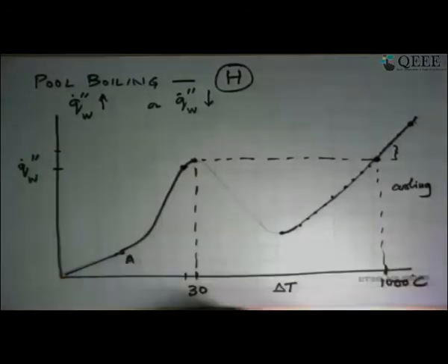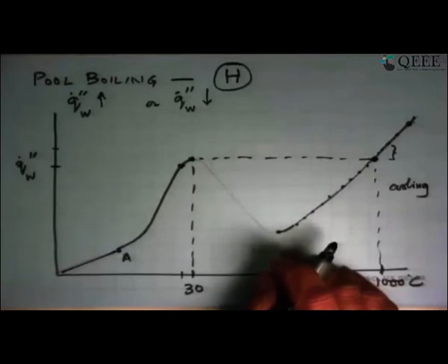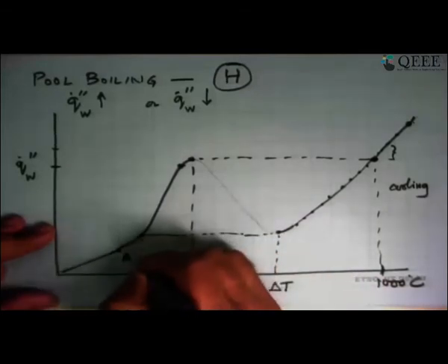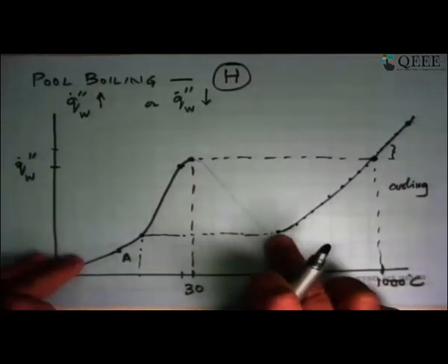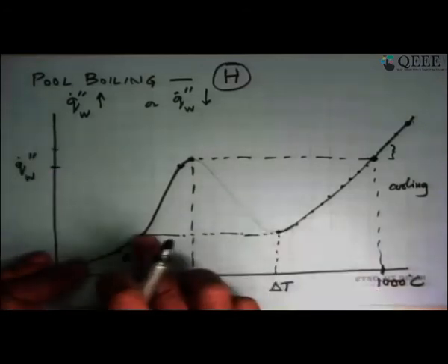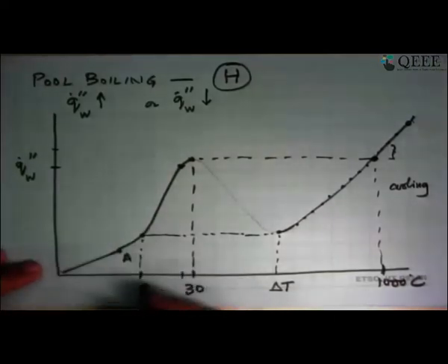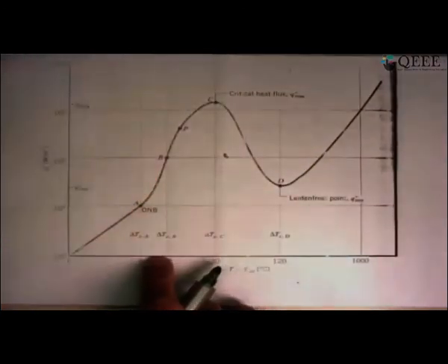So we reach that point because you are coming down this axis, and then if you slightly reduce the heat flux at this point, it will jump from here. So whatever temperature difference was there, it will jump down and come to this point, and now the temperature difference is much lower. So instead of a high temperature difference with a stable or unstable film boiling there, it comes here, which is into the stable nucleate boiling regime. Wall temperature decreases, the delta T decreases substantially, and you can see from here what sort of a change would take place. Here delta T is 120 degrees Celsius, but if you take this line over here and then look down over here, you're looking at about 8 degrees Celsius.